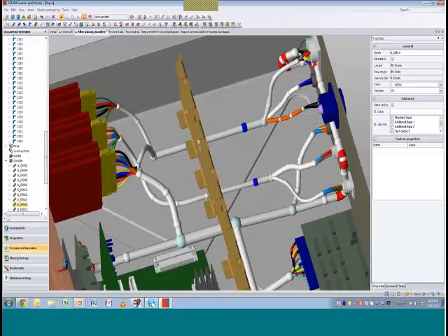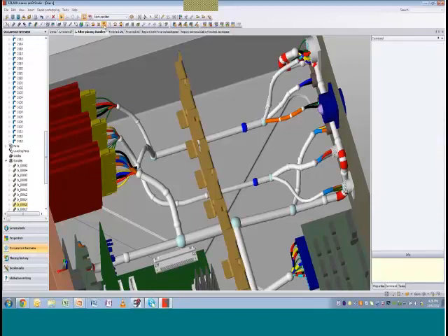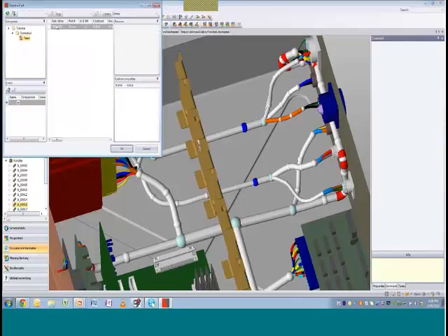As we get into modifications on the fly, synchronizing between the electrical and the harness, we can also start to maybe add some of the bundle wrapping. You're going to use tape to wrap your wires, or band your wires together. If you're going to use tie wraps, you have those items here available to you. You have looms, you have wrapping tape, you have braided sleeves, flexible tubing. All of that is used, and these are parts that you're going to just select from the part database.